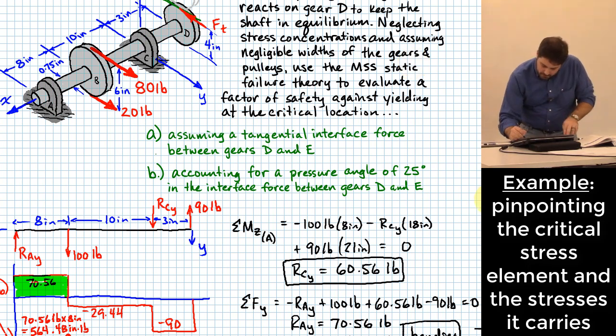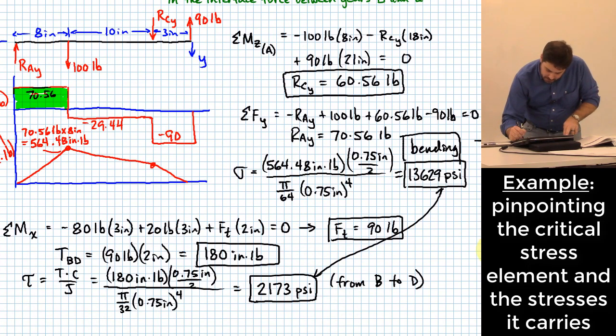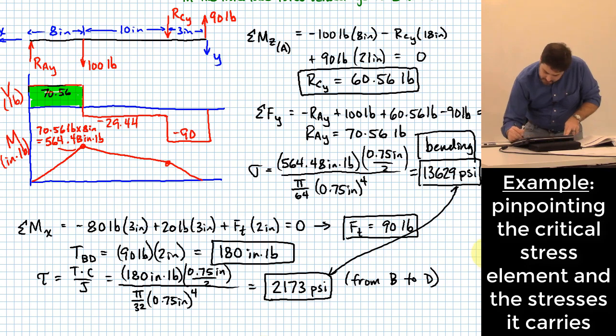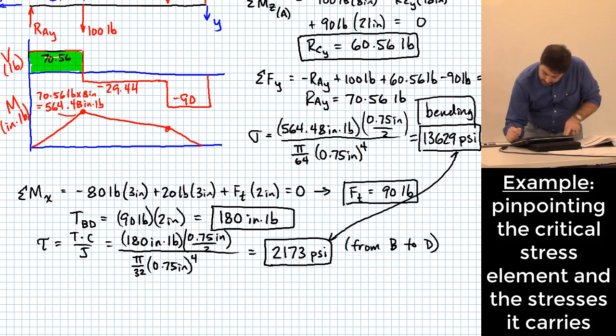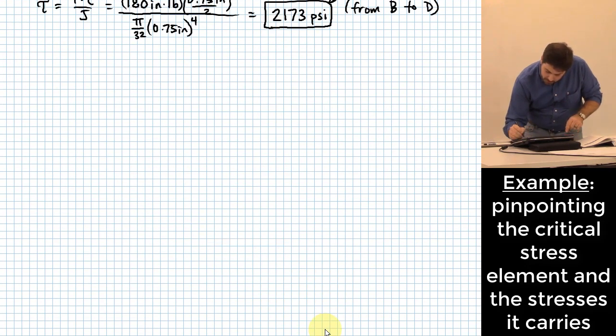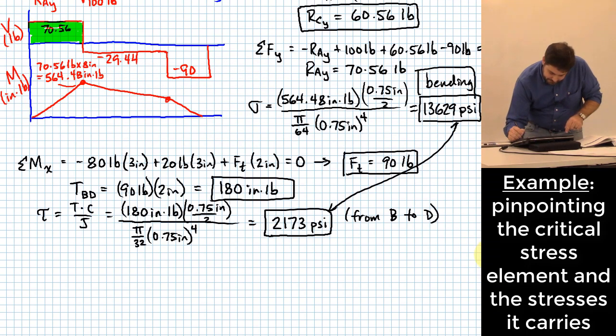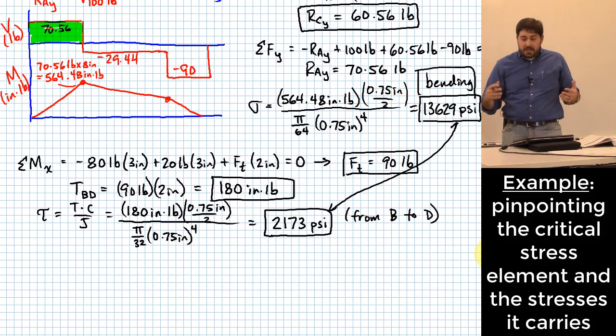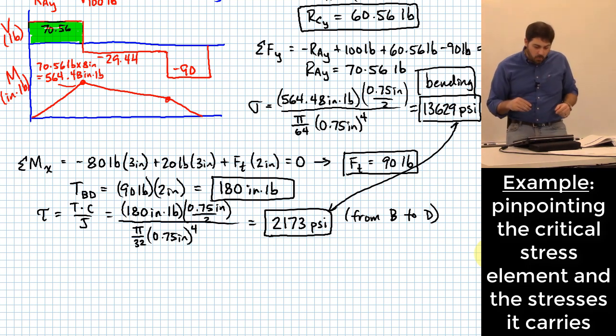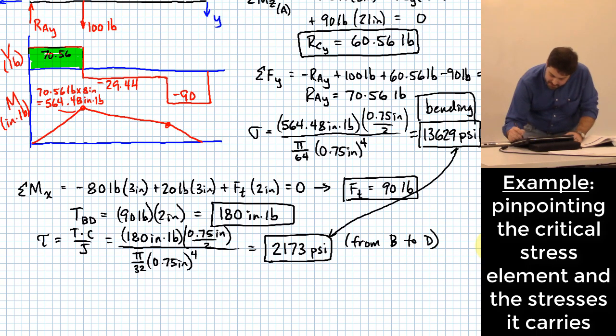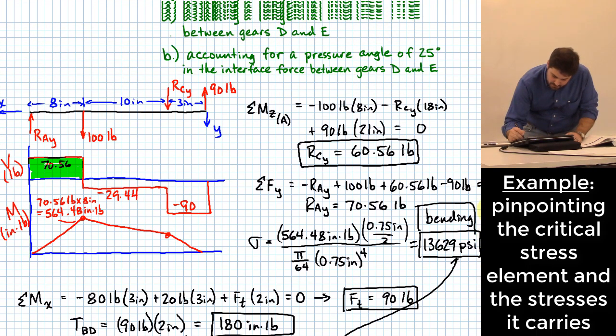Well, what do I do next if what I'm trying to do is come up with a maximum shearing stress? Actually, if we want to use the equations that we just talked about, we really need my in-plane principal stresses, right? So let's think about where is that element of material that's experiencing these two stresses.